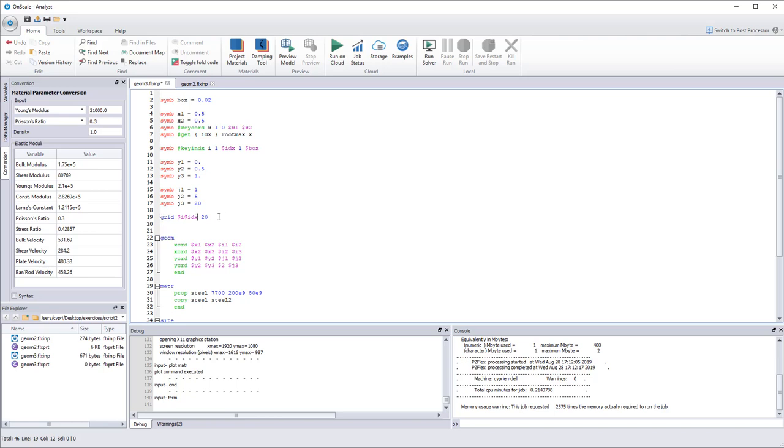When it will read this line of the script, it will first read the last part, the $IDX. Then it will go and look into this IDX and say, what is the value stored into IDX? Oh, this is 3. So it will replace this by 3. And then the grid will be created with a maximum number corresponding to the last node of the grid. So if your last node is 2000, it will automatically put 2000 here. If your last node is 5000, it will automatically replace here. So it becomes automatic. You don't have to tell the exact number of elements in the grid. The element of the grid is linked to these macros, which are linked to the box size. So now you can change the box size and the grid will automatically change.